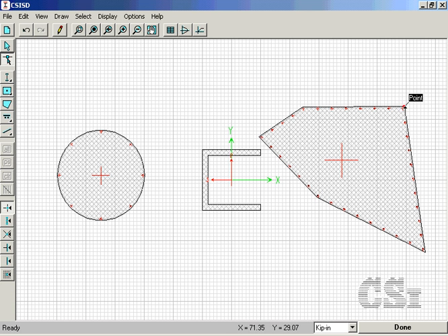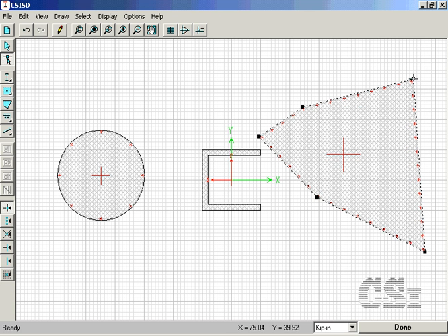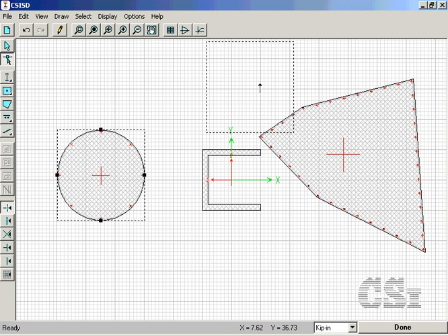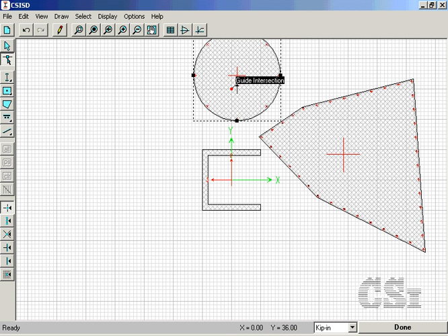At this point, it should be noted that all three of the drawn shapes constitute a single section, and though one of the shapes is steel, the Section Designer utility will calculate properties for SAP 2000 based on the equivalent base material of concrete. It should also be noted that the XY axes shown are local references only.